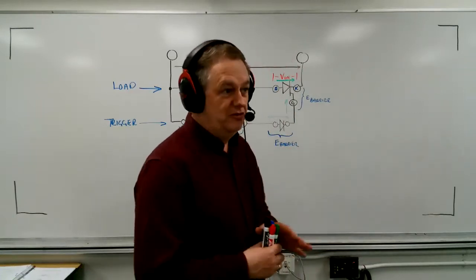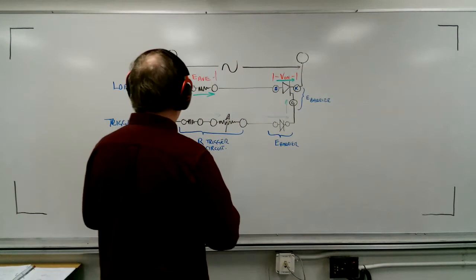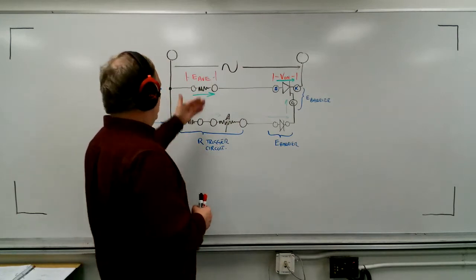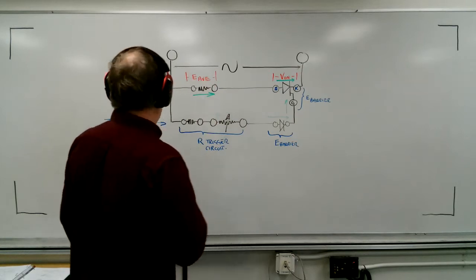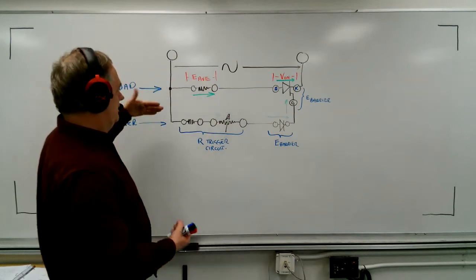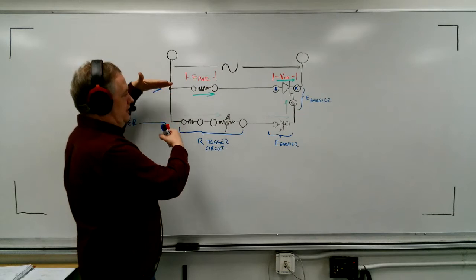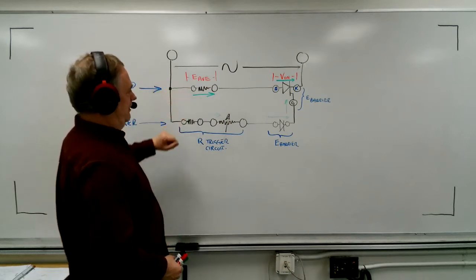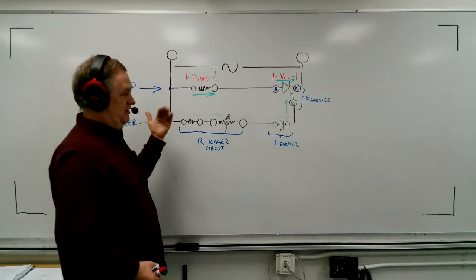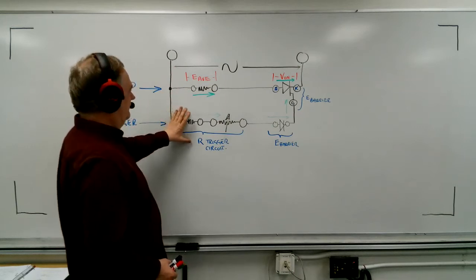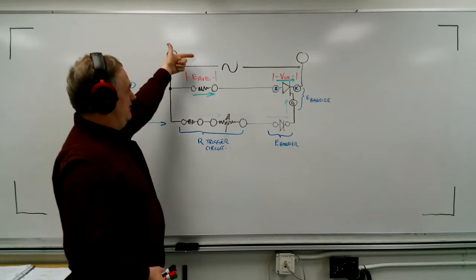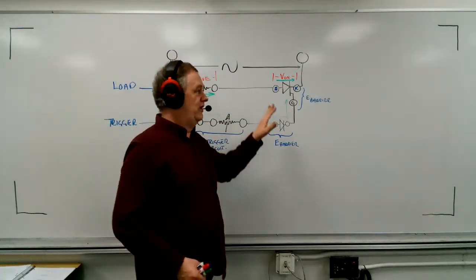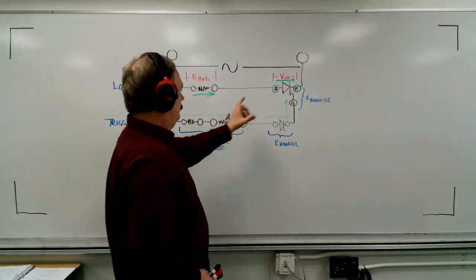So the circuit that I'm showing you here is a half wave rectifier. It's fed directly from AC, and what I really want to show you in the circuit is that there are two specific areas here, and how to separate them in your mind so you don't get the values mixed up. So we're tied to an AC source. We can see that we just have one SCR. It's in series with the load, and this is the switch.